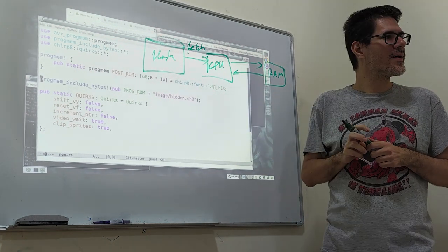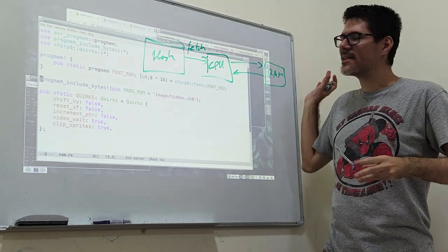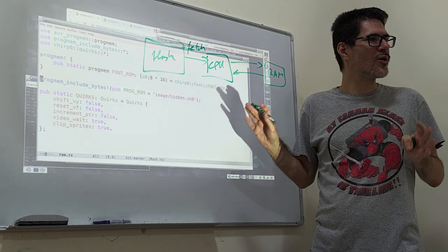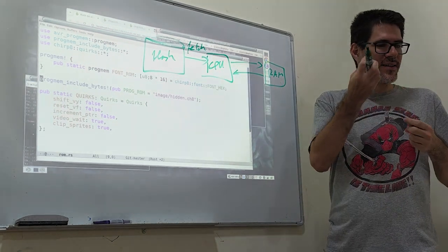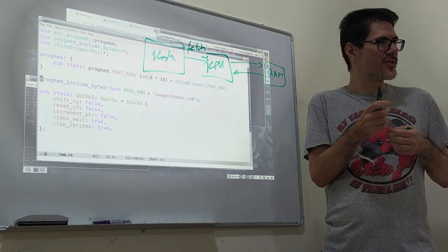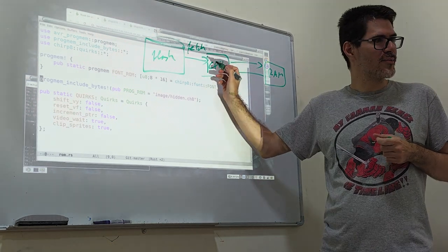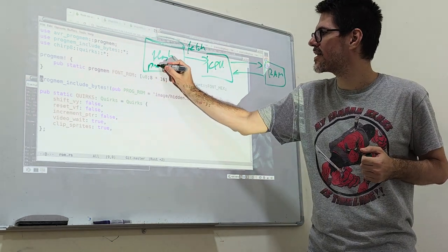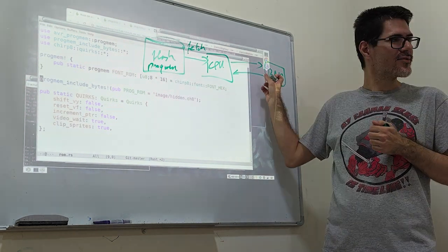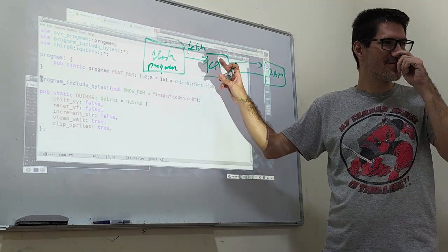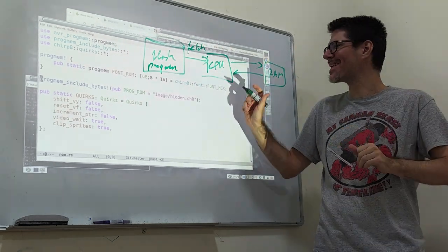Right. Can you effectively mmap something in, without the address translation? So there's no address translation. You have completely different opcodes for reading from here versus reading and writing here. It's not just a different address, the opcode itself is different. But you have opcodes for reading from program. This is called program in AVR, and you have a way of reading bytes from this individually. It is slower than reading from here, and it takes more energy. Well, of course, energy doesn't matter for us, but this is a microcontroller, so for someone somewhere this matters.